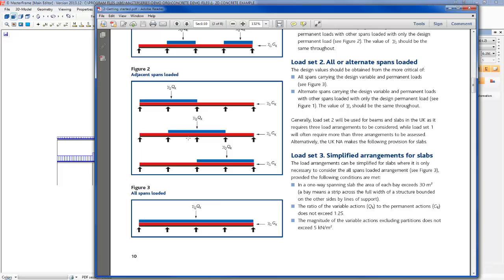The other reason is that when you're dealing with large frames, this is going to generate n+1 loading combinations. So in a very complex frame, you will be dealing with a colossal number of loading cases and it will be very, very complicated. It's doable because in the MasterSeries you're able to create up to about 160 different load groups. So you could create yourself that number of load patterns, but with a lot of work. So we're not going to do that.